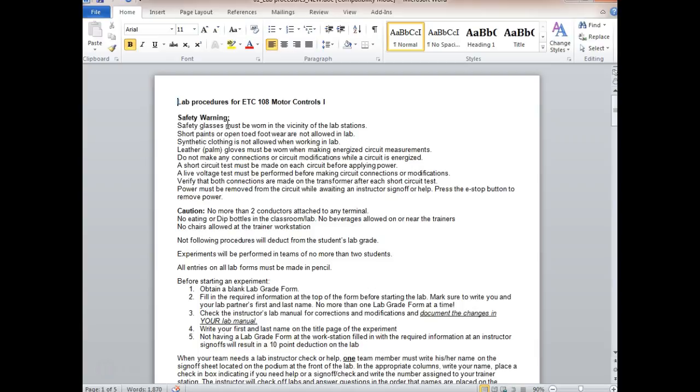A lot of people take for granted that when you click a disconnect or something like that, power is removed. Now, 99.9% of the time, that's a good assumption, but it's that 1% that's going to get you, right? So anytime you do a disconnect, what do you need to do before you put your hands in the circuit? You need to get your voltmeter out and make sure the circuit does not have voltage, because disconnects are made with contacts. Contacts stick together, right? You understand that? Our disconnect is a relay control disconnect. Knife switches are probably a little better, but even with knife switches, you might run into problems.